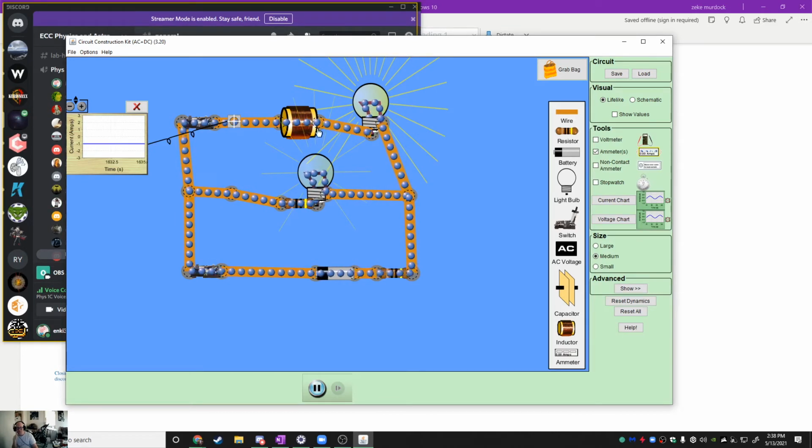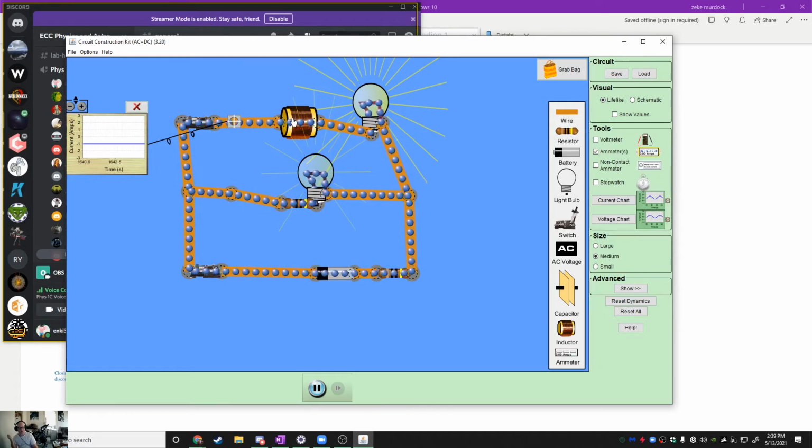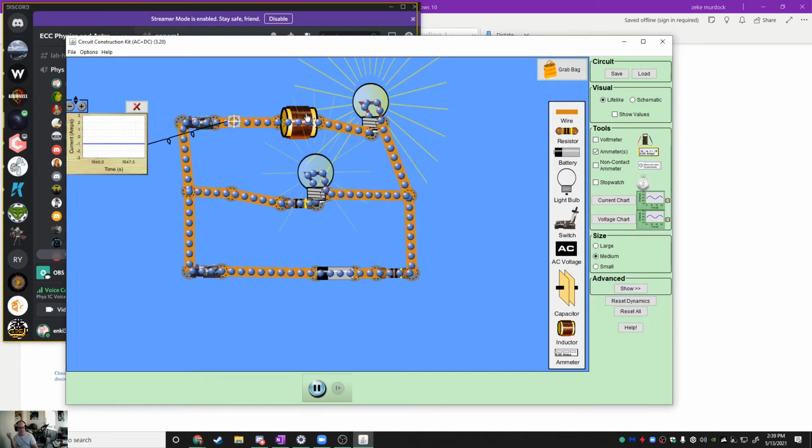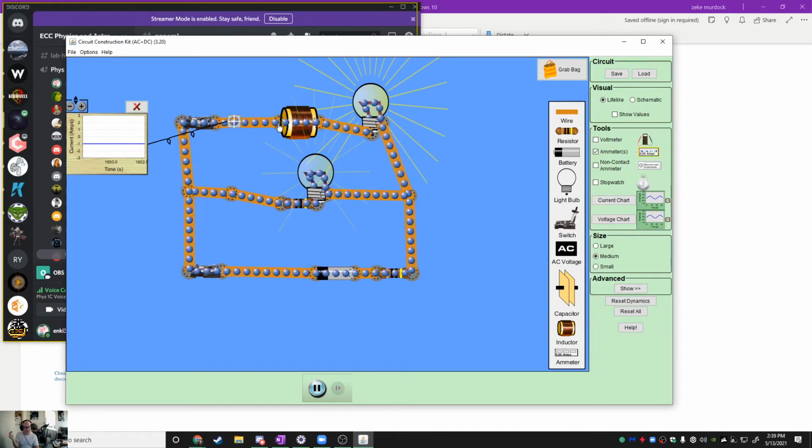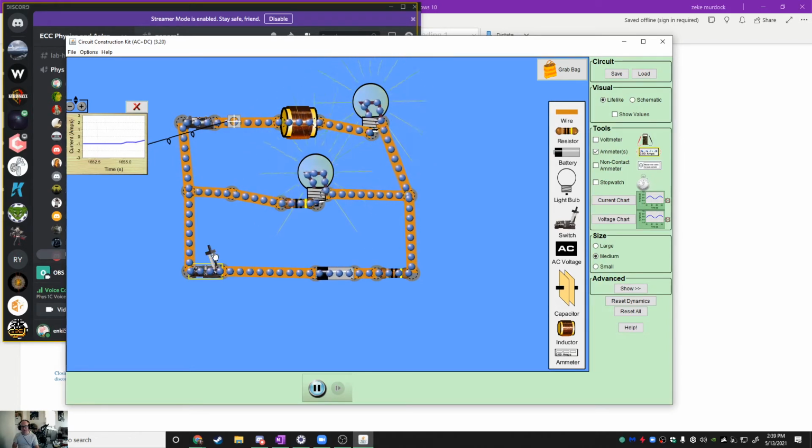Yeah, so the way I think about it is, the inductor can act just like a battery, basically. It can be a source of charge. It can be a source of EMF, right? And when you're turning the circuit on, it acts as a source of EMF opposite to the direction the current wants to flow, because it's always going to oppose changes. So when you turn the circuit on, here, we'll do this. You can see that you were right, by the way. I don't know if you all noticed. We'll look at it in a second.